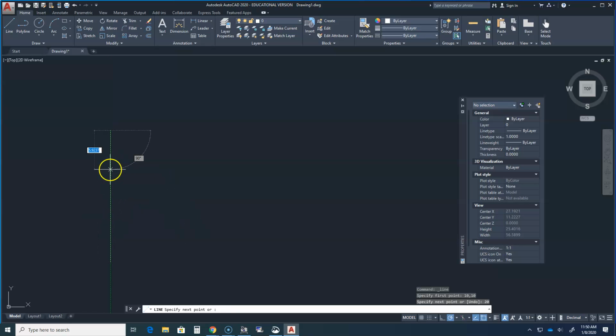20 units for the height, and then come over to the side as 10 units. So always pay attention to that when you're drawing by instructions, such as you'll have on the certification test. It will tell you to place something maybe at a certain point, and if it says the size of this rectangle should be 10 by 20, then it means 10 wide, which would be your X dimension, and then 20, which would be your Y dimension. Okay, so we would have basically a vertical rectangle.